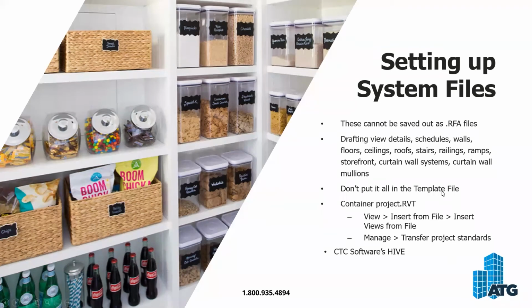Don't put all that content in your template file. I shouldn't have to say this, but man, I have to say this quite a lot. We talk with people about building templates for them, reviewing their templates, streamlining their templates. And there are a lot of people that put all 78 walls that they use into their Revit template, and all of their jobs start with that. And nobody knows how to find the correct wall type because there's so many to choose from.